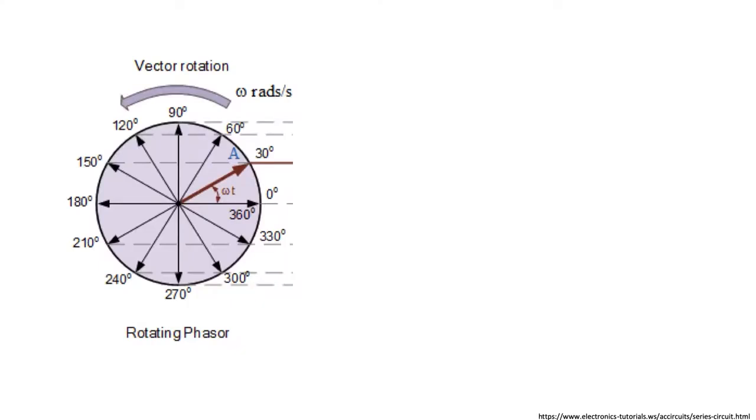The phasor diagram that you see in the current slide is actually called an Argand diagram. It's a method of plotting complex numbers. A complex number has two components, the real component and an imaginary component, typically written like this. Z is the complex number, 6 is the real component, and 4 is the imaginary component. The small letter j represents the imaginary component and is equal to the square root of -1. Sometimes the small letter i is used.